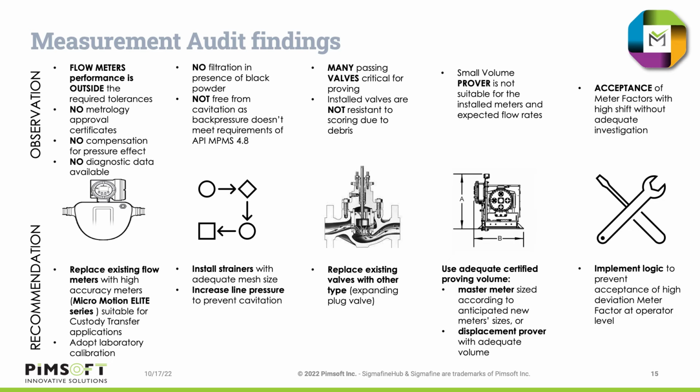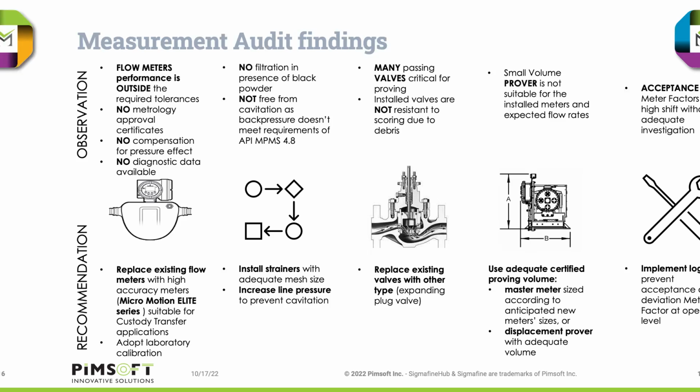Human errors have been observed in many installations. Wrong flow computer constants or accepting wrong meter factors are really classical examples. A facility to control the flow computer constants and to consult the meter factor control chart and the meter factor acceptance tolerance before just accepting the new meter factor is always recommended.